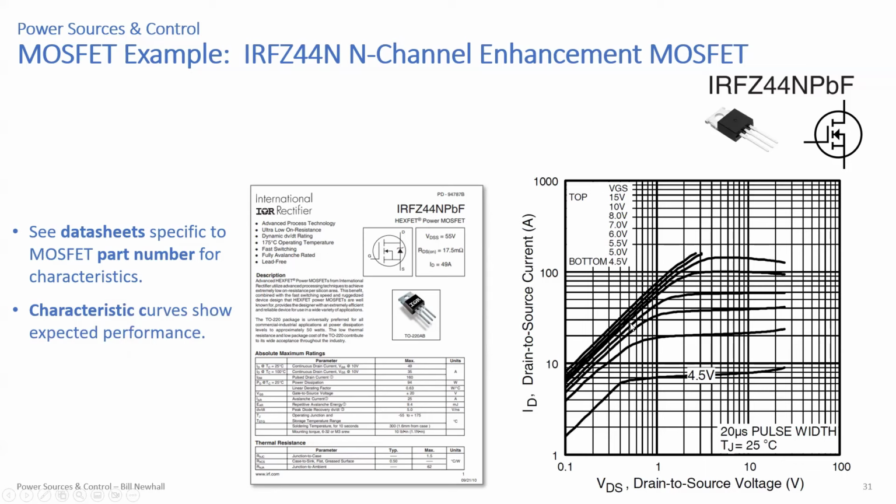So, this is not the cartoon, this is the real thing here. But we have the same axes: the drain current, here called drain to source current, versus drain to source voltage, and then for various VGS values. VGS is called out here. The bottom line here is 4.5 volts, and the top line here is 15 volts. You kind of have to mentally fill in, or handwrite in if you want to not make mistakes, all the values of these voltages in here. But this is the family of curves for these different VGS values.